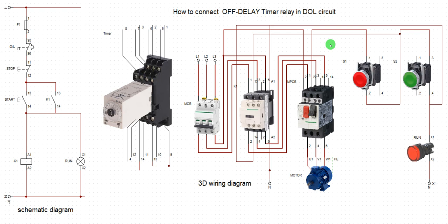There's also what you call a cool down duration. Supposing you want to shut down your generator, a particular time will elapse before that genset shuts down. So you're going to use an off delay timer. The advantage of the off delay timer is that when it shuts down, it will also knock off any signal, knock off the power output. But when you use an on delay timer, after shutting down the equipment, the power will still remain on the relay. The relay will still be energized, but the equipment will shut down. The off delay timer will shut down the equipment, executing the instruction given to it, and also shut down the signal coming to the relay in the circuit.